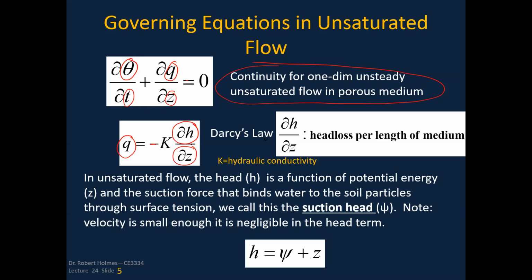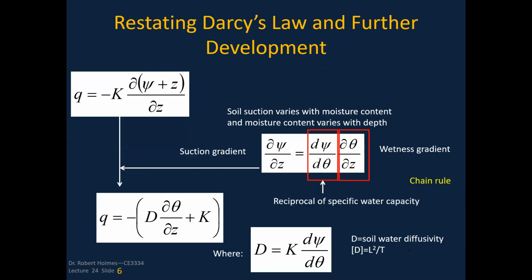This head is a function of the potential energy, but also the soil force that binds the water to the soil particles. That's the suction head we talked about. So when we talk about head in a soil, we not only talk about what its elevation is and where you're at in that soil column, but also what the soil suction is. And psi, the Greek letter psi, is the abbreviation we'll use for soil suction in this lecture.